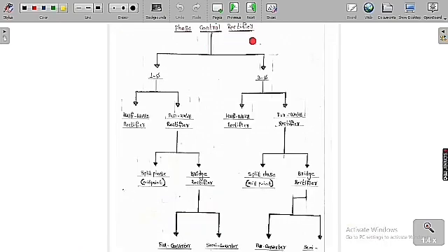We are going to study the phase control rectifiers in two fashions, same as you have studied previously: single phase and three phase. Single phase means we are going to study the half wave rectifier and full wave rectifier. In the full wave rectifier, we are going to study the split phase midpoint and also the bridge type rectifier. In the bridge type rectifier, we are going to study the full converter and the semi-converter. Full converter means we are going to use all thyristors, whereas semi-converter means we are going to use a combination of thyristors and diodes.